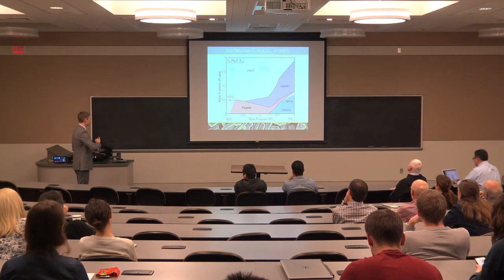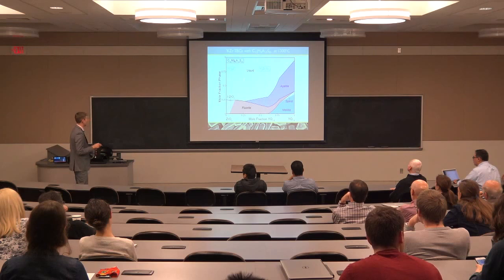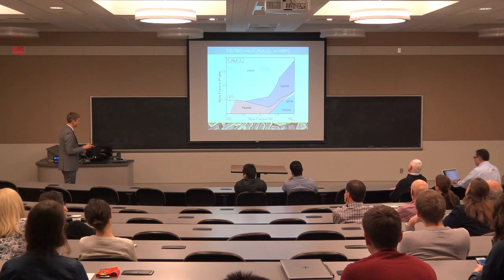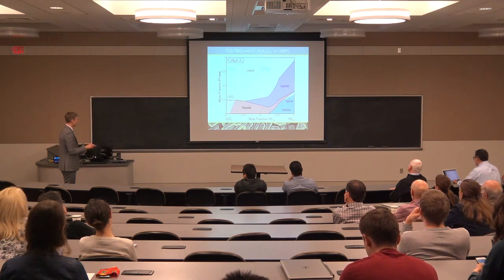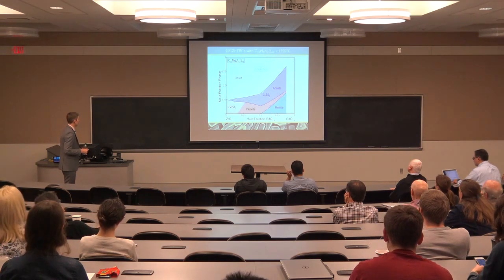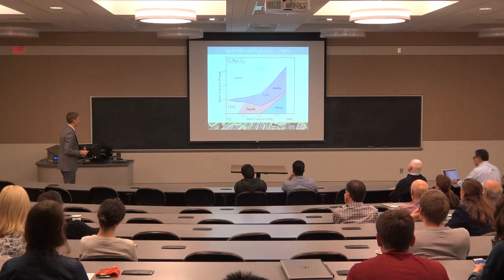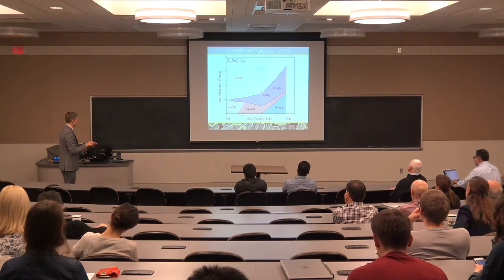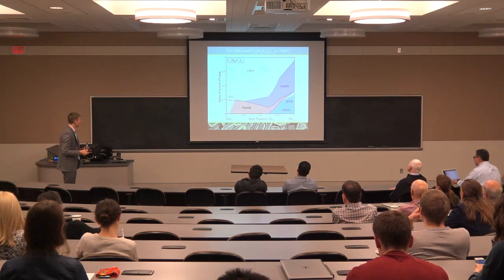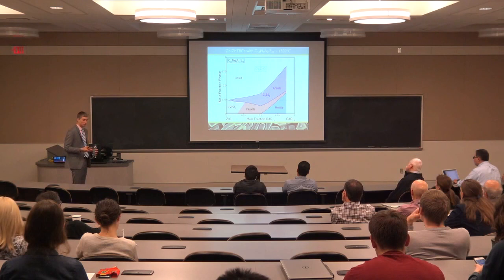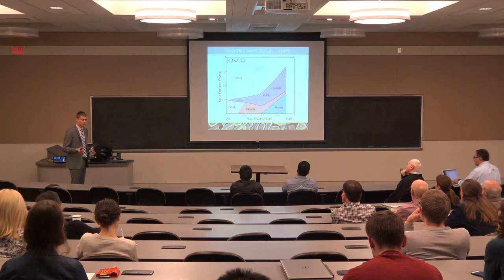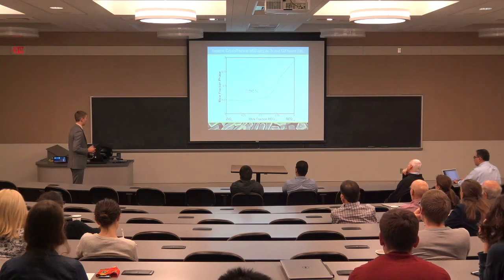If we look at the behavior of the same set of coating materials, though, with a different deposit, one that better promotes apatite crystallization, we find that for this particular coating material, because we crystallize the apatite, we're going to get an increase in volume. But if we do the same calculation, with the same deposit composition, with gadolinium, we see that at roughly the same point in terms of coating composition space, we get a lot more apatite. And so this comparison drives home the point that due to the stronger driving force for apatite crystallization in the gadolinium system, the gadolinium-based coatings offer better performance.